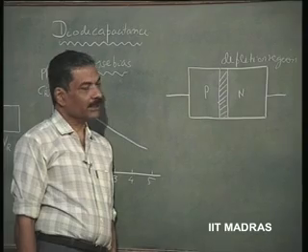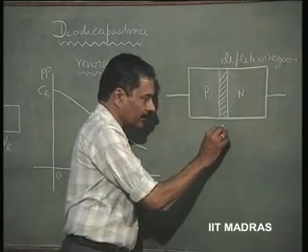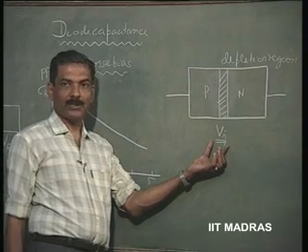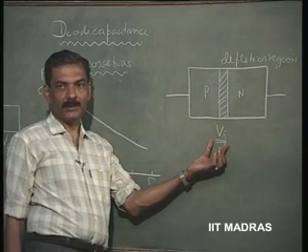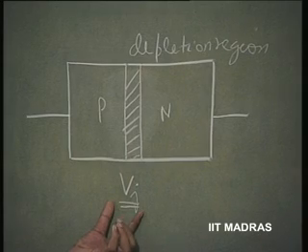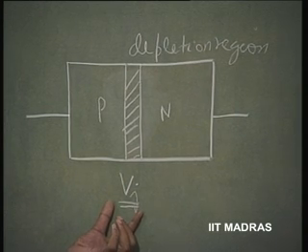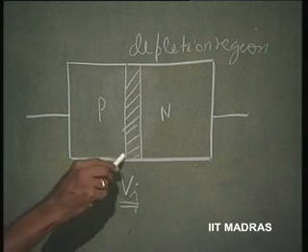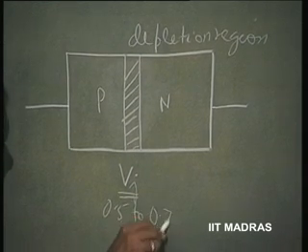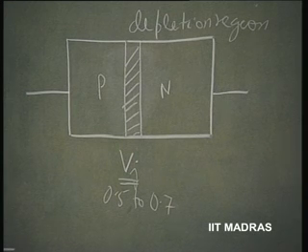Thereby it develops a potential hill. This is called the junction potential, V junction. And this V junction, according to the semiconductor theory, for silicon happens to be around 0.5 to 0.7 volts, we said. That is why the semiconductor diode was not exactly close to the ideal diode. There is a deviation from it. It starts conducting only when a junction potential of about 0.5 to 0.7 volts is applied, and then the current is unlimited. Until that time, current is negligible.